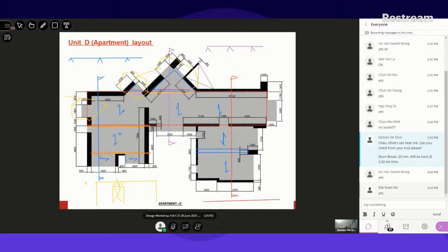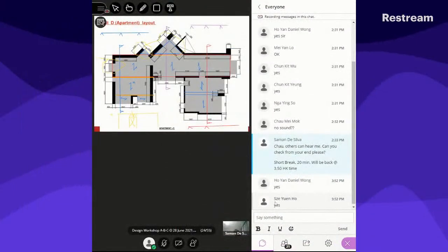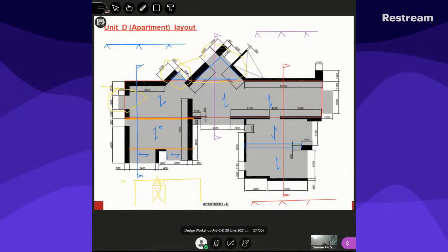It will have a good support there, good support next. I'm traveling from here to there, right? And this blue color beam which we need to provide, that's the third, and then this is the fourth. So it is 1, 2, 3, one-way spanning slab. Now that is the beam arrangement in this case.